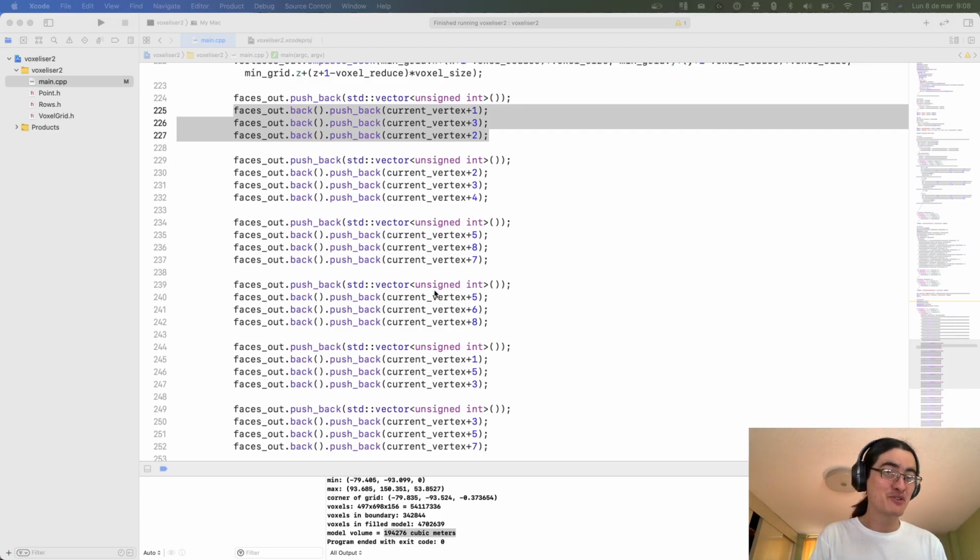Even Blender doesn't do it very well if the polygons are slightly non-planar, and because we're dealing with approximate coordinates, all polygons that are not perfectly aligned to one axis will be slightly non-planar, and a lot of software just doesn't want to deal with that. So what they do is only support OBJ files with triangles. So the ideal thing was to output 12 triangles per voxel.